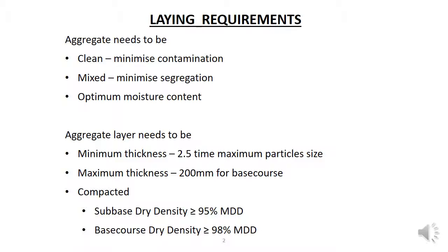However, this mix is not going to work if the fine and coarse particles are separated during transport or if clay or dust contaminates them. Separation can occur through excessive vibration or movement, with the coarse particles tending to be more easily moved out of the mix when vibrated. One way of avoiding this is to lay the aggregate from a moving truck so that it's spread out in a layer, as we saw in the road construction section. This minimizes the amount of grading required to form the layer ready for compaction, and so minimizes segregation.